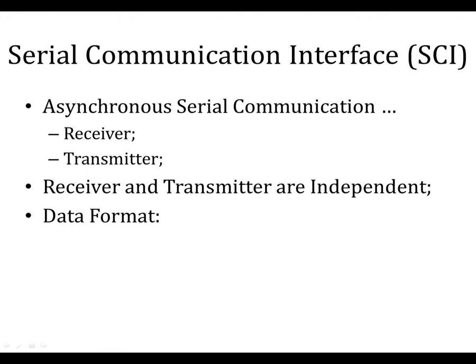So our communication unit is serial asynchronous. And there are two subunits, receiver and transmitter. Transmitter is the one which is responsible for sending. Receiver is the one which is responsible for receiving. Now it depends on whether it's in receiving mode or it is in transmission mode. Okay? It's basically you are the one who will be writing the code to set it up.